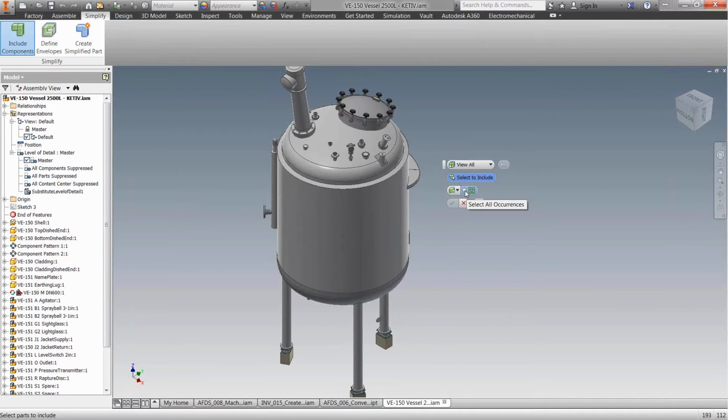So if you have multiple parts that are exactly the same, like these handles here, if I choose one, it'll assume that we want to keep all of those. So I'm going to go ahead and select that and pick the handles, and it basically picked all of them, right? So I'll go ahead and deselect those, right? And I'm going to tell it what I want to keep. So I definitely want to keep the cylinder, right? I'll keep these legs, and I'm on a part priority.